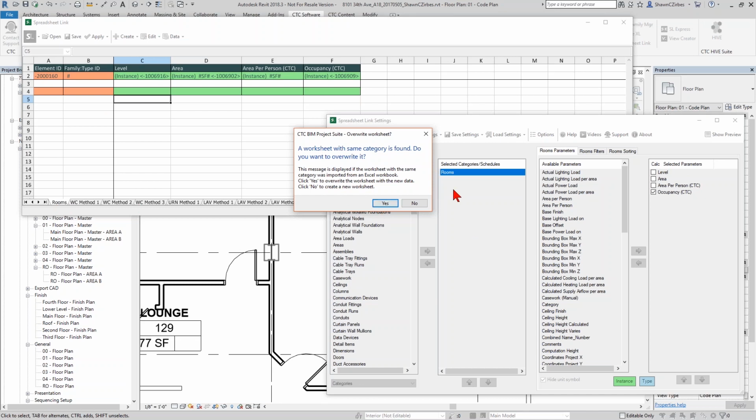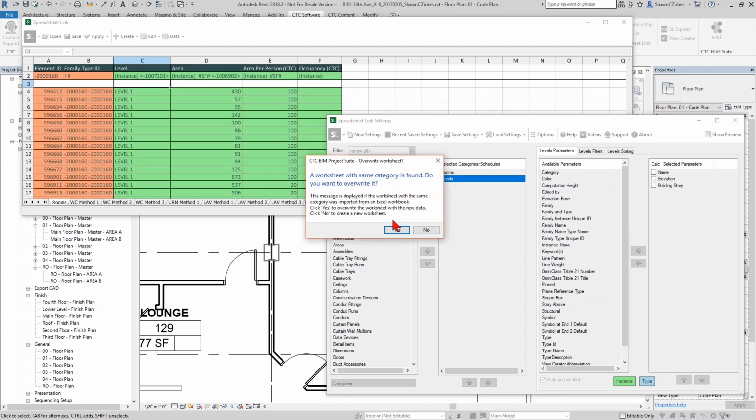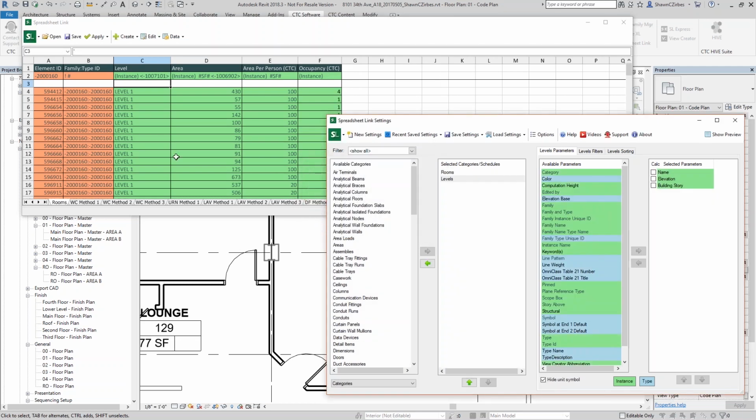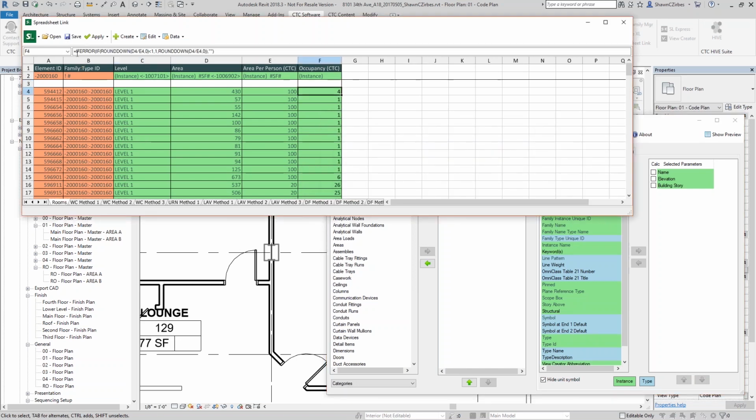And when I'm doing this, you might notice that rooms exists. It's got those exact same 4 parameters. Occupancy is calculated, hide unit symbols checked. I'm going to replace this here real quick. It has another tab for my level name, so it knows how to associate my levels properly inside of here. But this runs a very similar calculation, though a little bit more complicated.